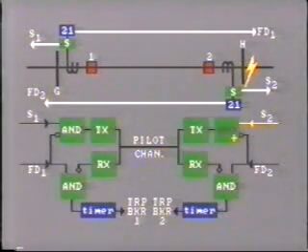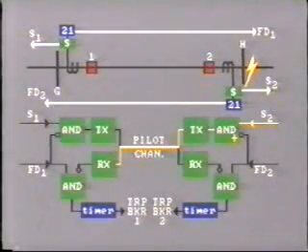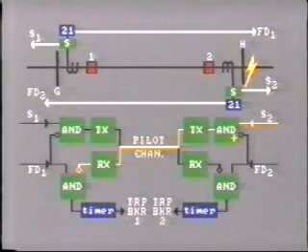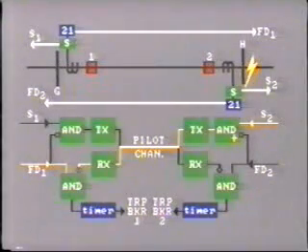As this logic box shows, it requires 2 positive input signals, one from the fault detector and one from the starter relay. With these 2 positive signals, it initiates transmission of the blocking signal. This is received at the other end, station G, and the signal is passed into the permissive tripping circuit and mixed with the signal from fault detector 1, which, as you remember, is trying to trip breaker 1. The positive input signal from the receiver becomes a 0 signal.